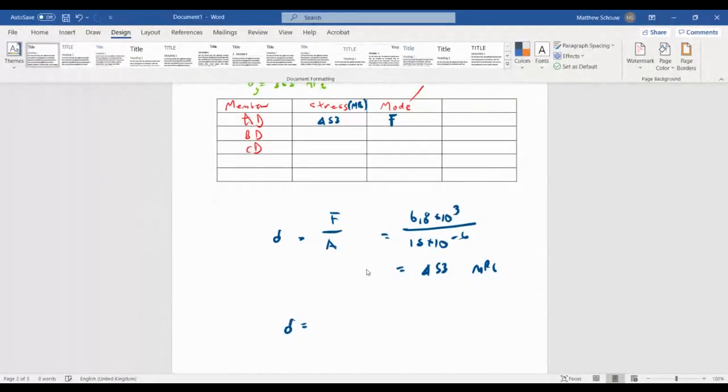So in this case, BD is going to be 1.8. Of course, this is a compressive stress. We're going to see this when we start doing buckling, where I'm going to include the 3D truss, because a member like that won't just fail due to compression. But yeah, you'll see. Then divided by 15 as well. So we're assuming all the same sizes here. I'm assuming, of course, it's a smaller value, so it could be within range.